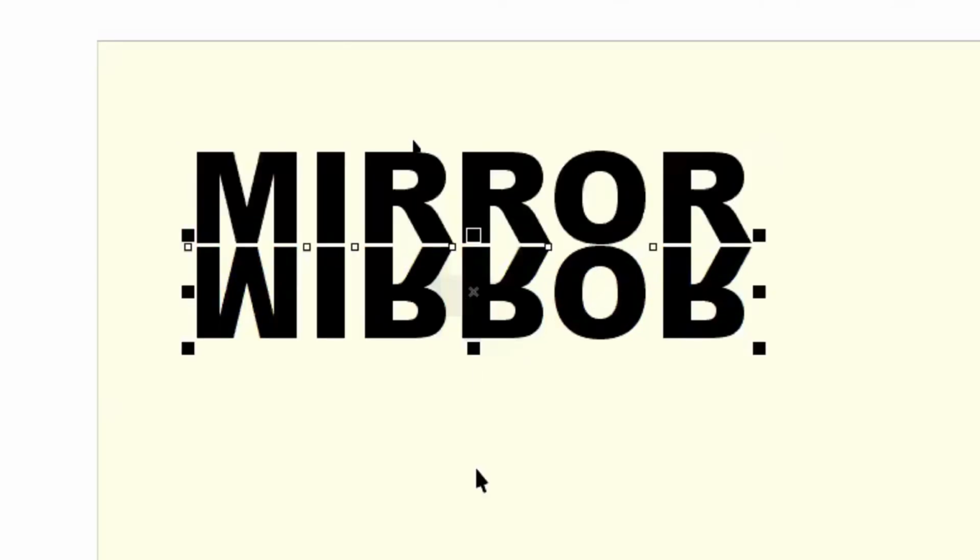We can duplicate a lot of different ways, right? We can actually duplicate using different measurements, but we can also just grab this handle, and I'm going to hold my control key, and bring this down, but then holding the left mouse button down, I'm going to right click. Now what that just did is give me an exact copy of that whenever I right clicked it.